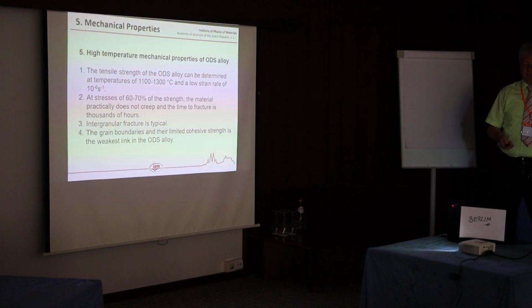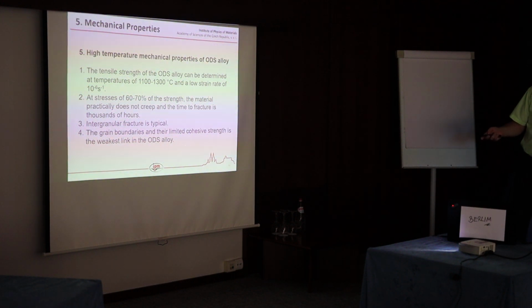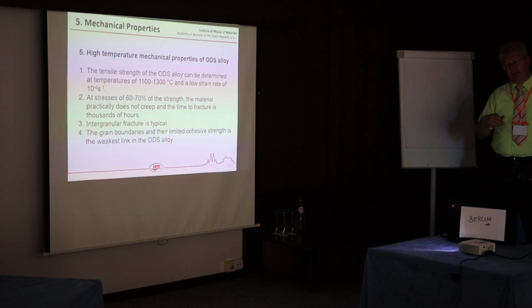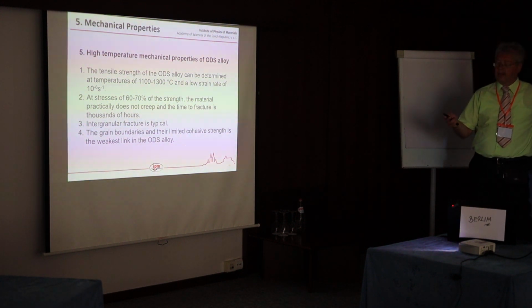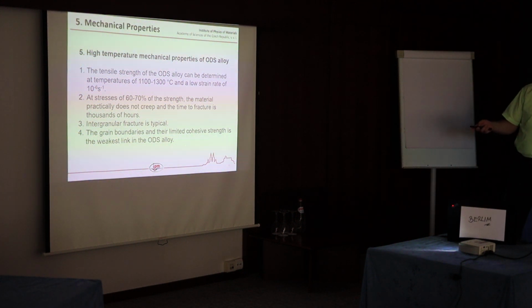It will be several thousand hours up to the creep rupture, because the stress exponent is relatively high, on the order of 10 to 40. It depends on the temperature and also on the stress.